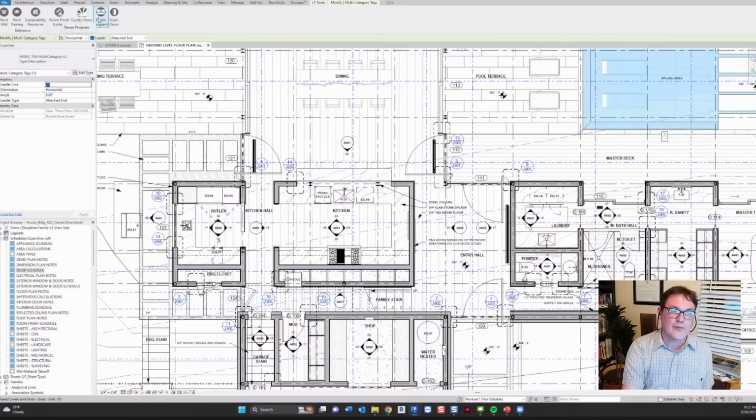And then finally, this program one is something really cool that we're currently still working on. It's non-residential really, but it involves creating a room schedule and developing the program in it. Then you click this button and it makes a bunch of blocks for that room schedule that you can move around, different stacking diagrams. If you delete one and click this button again, it'll recreate the missing one off in a sandbox area, or if you've added any new rows, and then we can color code them by department. So it's just a massing design tool that we came up with.